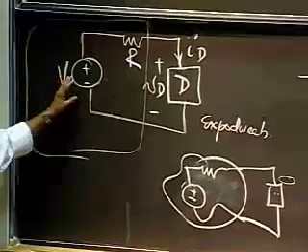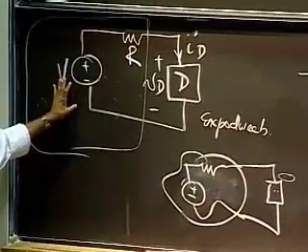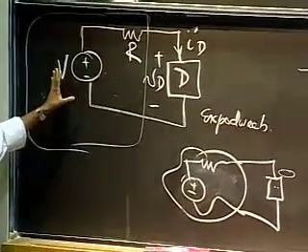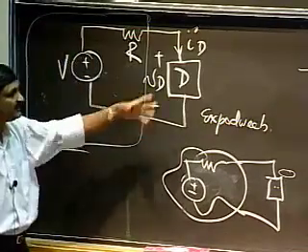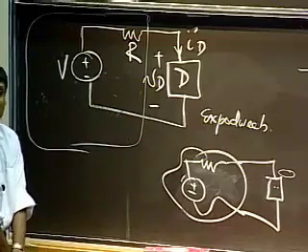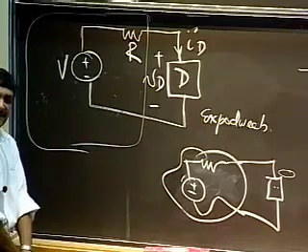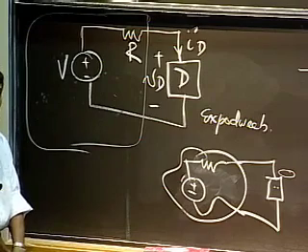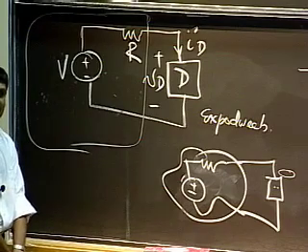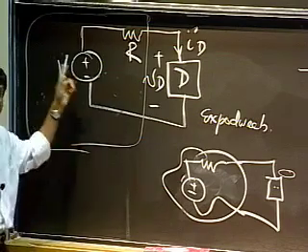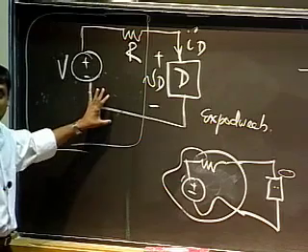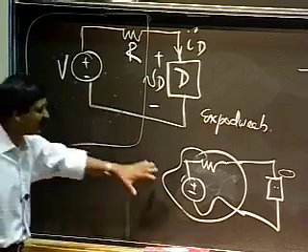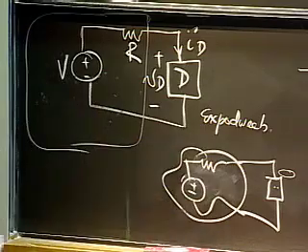What this means is, because of this brilliant Thevenin simplification, going forward through the rest of this course, we'll mostly deal with very simple circuits like this: a voltage source, a resistor, and a device. That's it. Very, very rarely will you see multiple sources and lots of resistors in a circuit. It's usually going to be simple stuff. And remember how we got here: by making a Thevenin simplification of a linear mess.